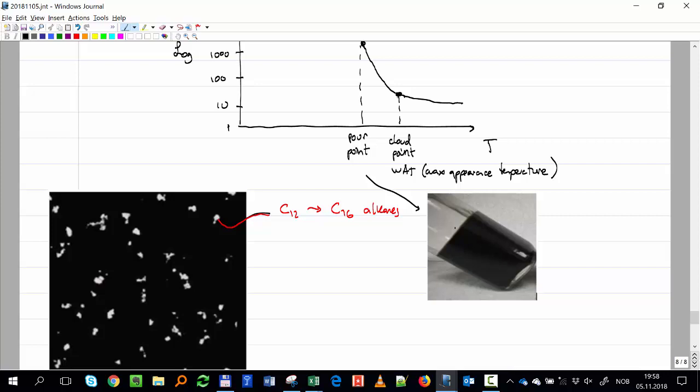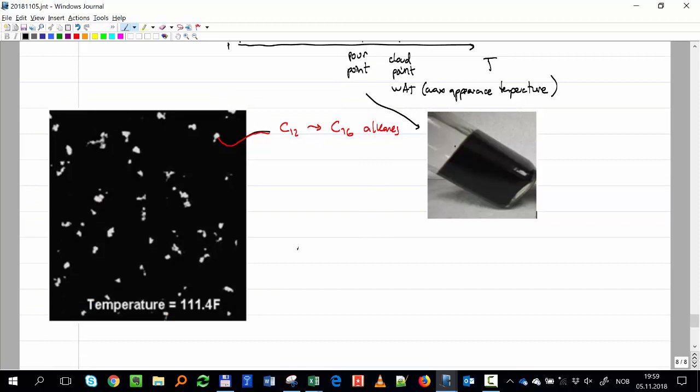For two reasons. One of them is the increase in viscosity. If you have a pipeline that is getting cooled down, the reduction in temperature can cause a dramatic increase in viscosity, and thus in pressure drop. So you have to be careful. Low temperature gives you high viscosity, which can give you a very high delta P in the flow line, even to stop flow completely.